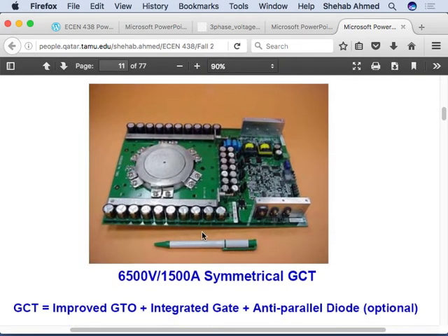So it's like just a pulse instead of constant. Yeah, it will be like a MOSFET. You will apply a constant voltage, but the current will be what? You're just charging the gate capacitance, like a MOSFET. BJT devices, you need base current, continuous base current. MOSFET devices, you just need a gate voltage to charge the gate capacitance. You apply voltage, capacitor is charged. That's it. You're not sucking current anymore.